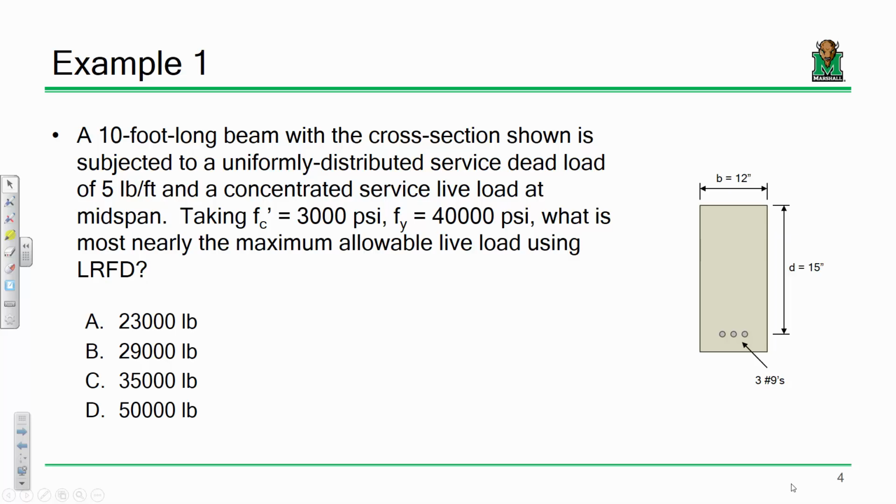Other than that, really no. All of the concrete design formulas, the steel design formulas, you know, like for inelastic buckling, 0.658 raised to the FY over FE, all times FY, you're not going to have to memorize that. It's all in the manual.